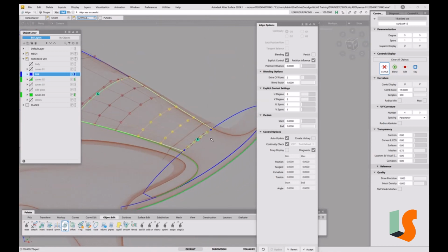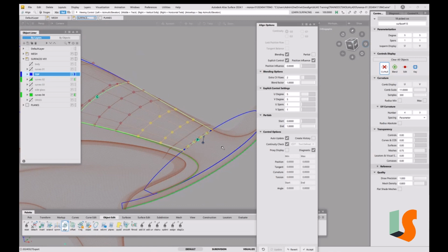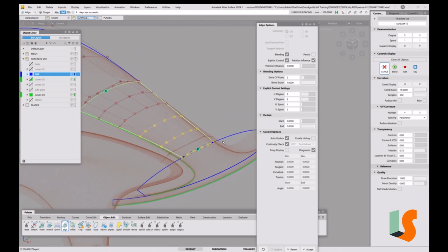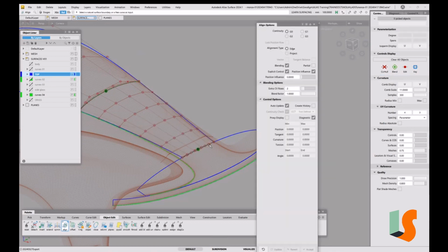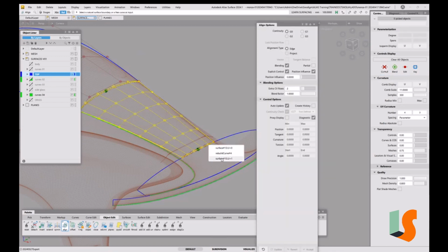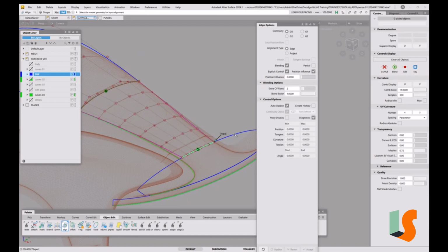Now I've aligned that only to the curve. I now want to align it to this surface. And the reason, if you remember, why I use the curve is just so that in the top view or plan view, those points will only move up and down in Z as opposed to moving outboard in Y. So keep the plan view shape exactly as we had. So now we want to just go and accept that, and we want to now align this to the surface.